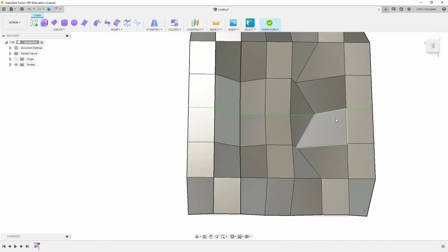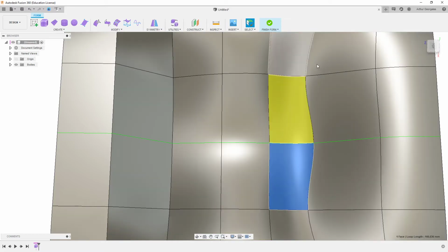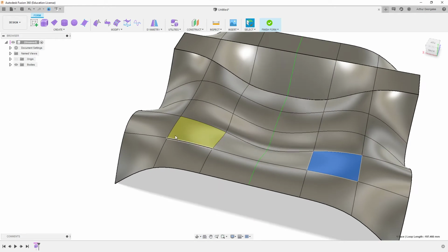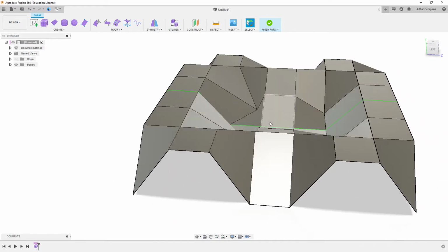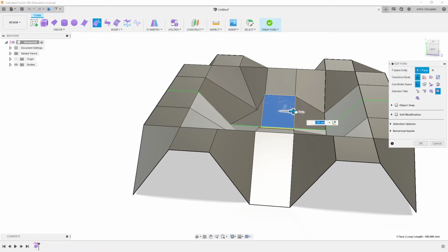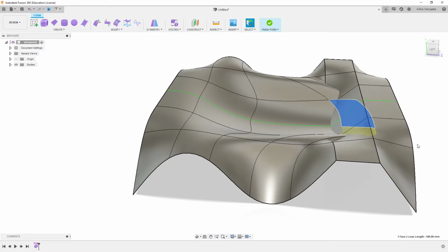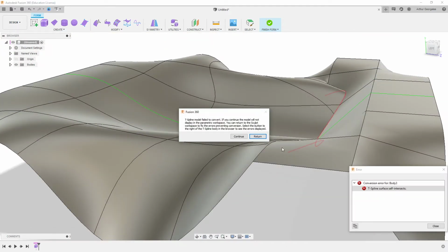And having all this weird complexity, having a different length here to here, means that that face is going to be blending in and out. And generally, you'd probably want to keep things relatively constrained. I see it a lot in advanced CAD where we've got super complex surfaces going on and there's a lot of points that are out of whack, and sometimes you can actually break the geometry by pulling things too far over. It won't work properly. So when you do something like that and it's overlapping and you try and rebuild it into a surface, it won't work. It'll tell you it's failed.